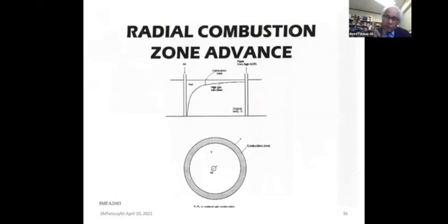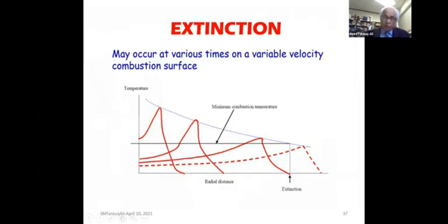And this is a very, very interesting problem on which I did a lot of work over the years. Here's the air injection well. I'm showing you a plan view. And the combustion zone is advancing, advancing, advancing. And at some particular time t, it is where you see the shaded area here. So it has reached here, and it looks like this in the diagram above. So what's happening? You can see that if you're injecting air at a constant rate, the combustion zone will keep on slowing down, until it is so slow that the heat loss takes up all the heat generated and extinction occurs.